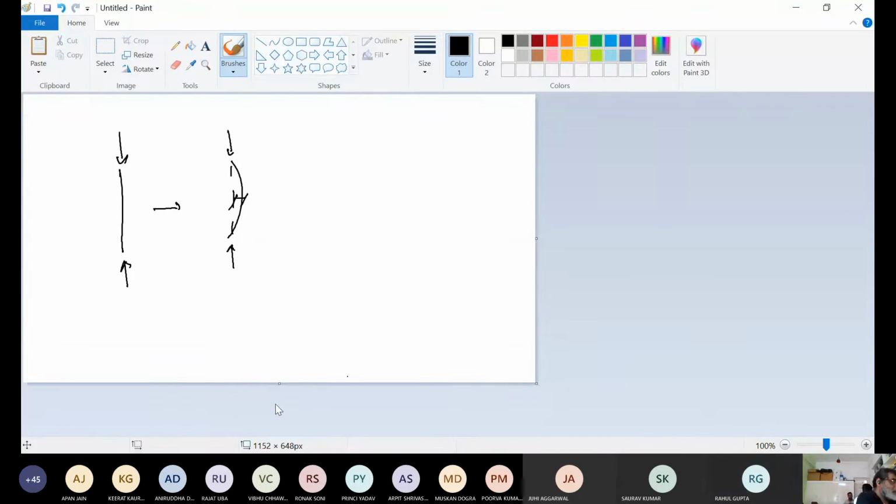Yes, sir. Okay, so basically you have some member which has some forces acting on it. Cool. Now, supposing you have got some rotation, which is some flexure, which is also acting. So this member bends like this because of flexure. And this displacement generates a work which is P times delta.